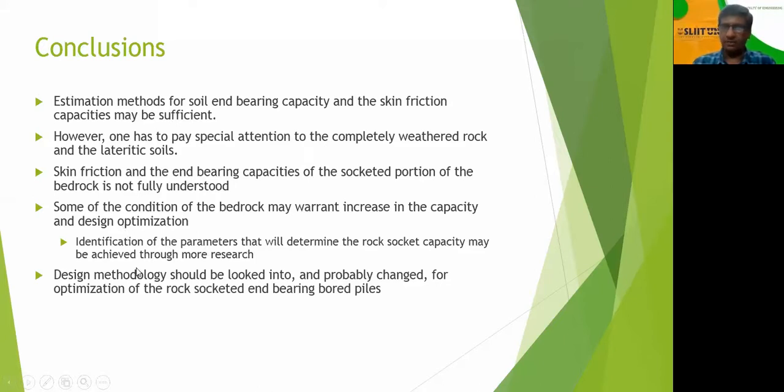the rock socket. And another thing that we have to look at is whether our design method of permissible stress approach is correct. If you look around the world, they use limit state design. So in my opinion, if you are using limit state design, we can optimize the pile design further.